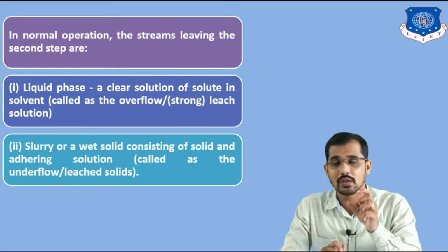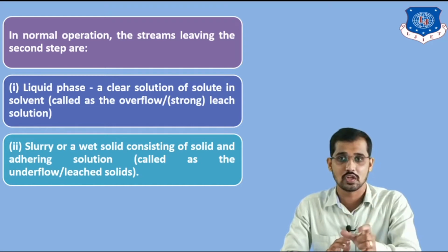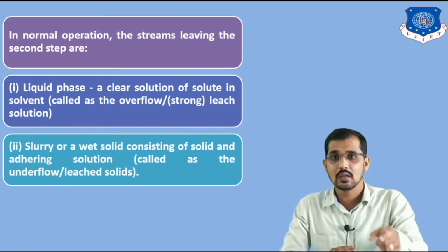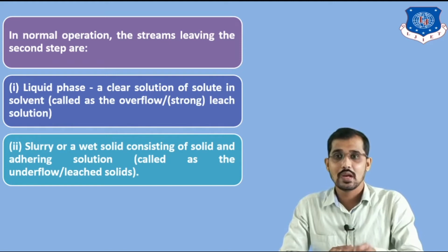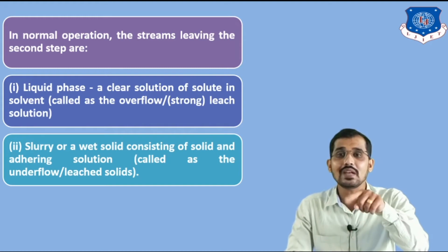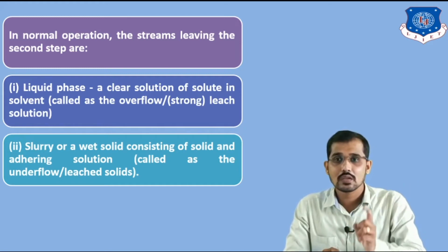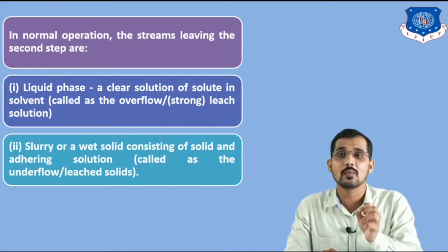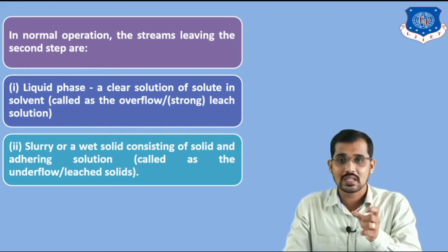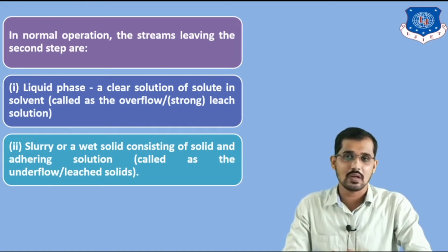Okay, so these are the very important terms. First one is the overflow and underflow. Overflow is nothing but your leach solution or strong solution, means whatever the solute which you want to remove from that solid by using that liquid, that is nothing but your overflow. And whatever is the insoluble part of that solid present in the solvent, that is nothing but wet solid. Wet solid means solid having some liquid part as well of that extracting solvent. So this whole material is nothing but insoluble, or I can say that is the wet solid. And this flow is nothing but your underflow. Okay, so overflow is your main stream and other stream is nothing but your underflow.